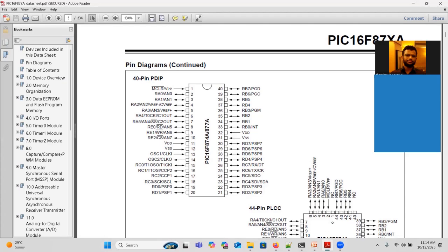Like that only we can validate our outputs. We have to create some symptom based on our result. If we get such a result, then our computation is correct. If it is a laptop, we see the number 13 directly on the screen. But we don't have such a display with a PIC microcontroller. Then what is the solution that we have now? We can push that value to some port and check whether that port has that value or not. Clear?